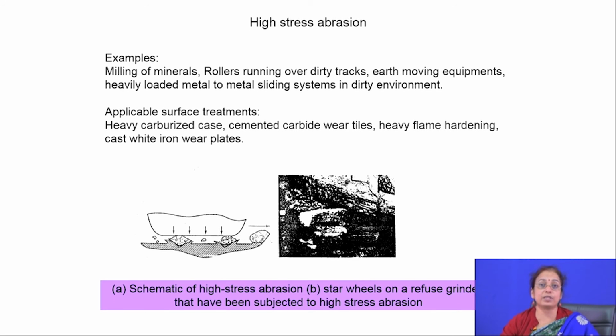There will be micro deformation, subsurface crack formation and failure of the component because of the wear. So, in high stress abrasion, the basic phenomenon is that there is deformation apart from scratching or cutting.